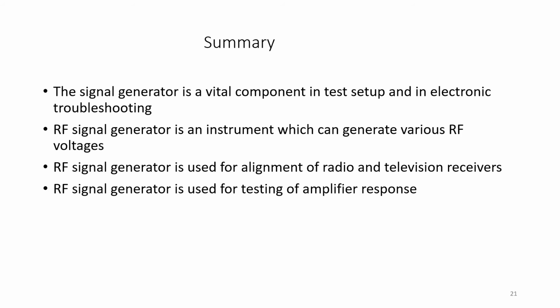The availability of the motor-driven frequency control is employed for programmable automatic frequency control devices. The internal calibration is provided by a 1 MHz crystal oscillator. The supply voltage of the master oscillator is regulated by a temperature compensated reference circuit. Here the modulation is done at the power amplifier stage.